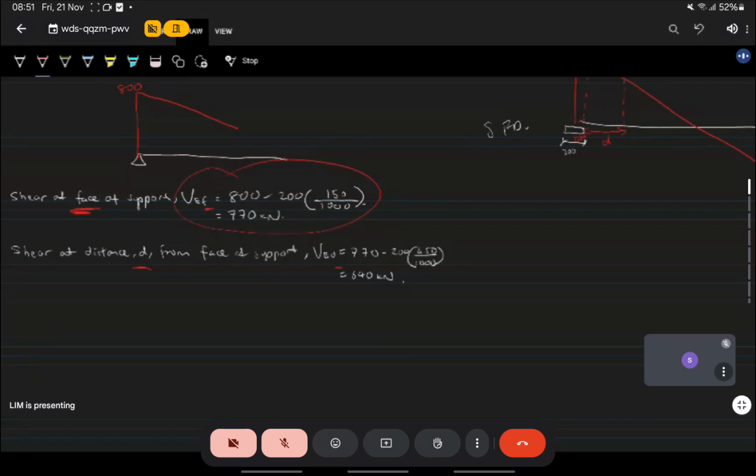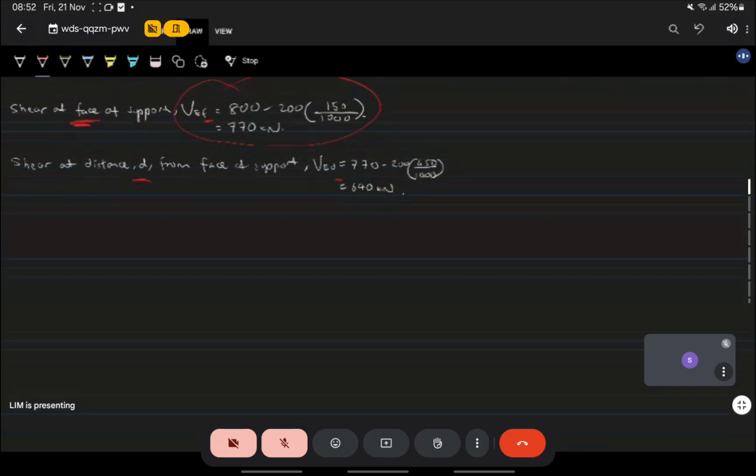I explained last week that the way a beam resists shear in Eurocode is they assume the strut and tie analogy. In other words, it assumes your beam behaves like a truss. So first, you have to assume the angle of the truss.